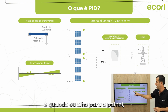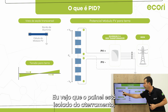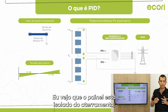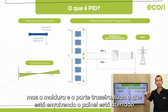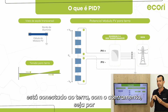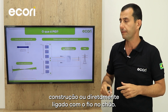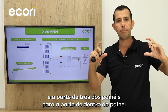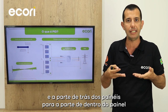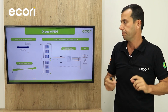And when I look at the panel, the cross side of the panel, I see that the panel itself is isolated from the ground, but the frame and the backsheet and all that's covering the panel is grounded, connected to the ground, whether through the construction or directly connected with a wire to the ground. And now I have a potential difference between the frame and the backsheet of the panels and the inside of the panel itself. This voltage difference is what is causing the PID.